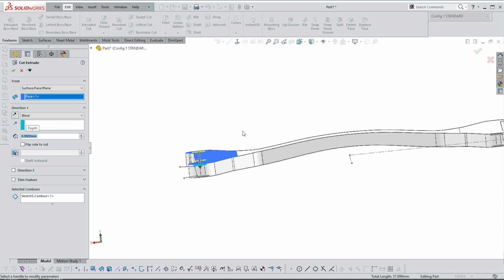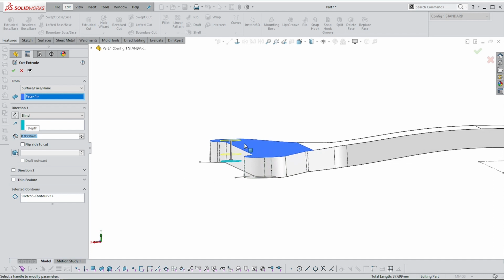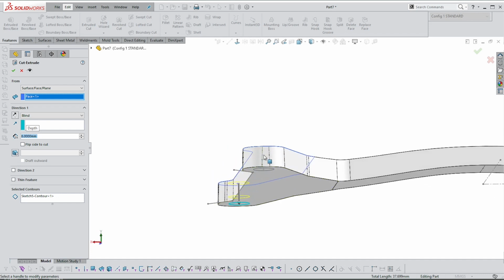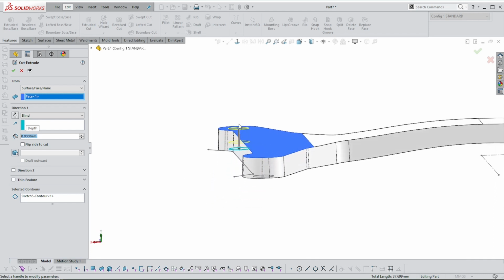Right. What should really happen is that it should go down much further than the thickness of this item. So I would go back and make this a lot thinner, so 8 mils, and this would be, say, 12. And I'm also going to give it a taper of 2 degrees, way too much. You should only do like half or so, but that's fine.